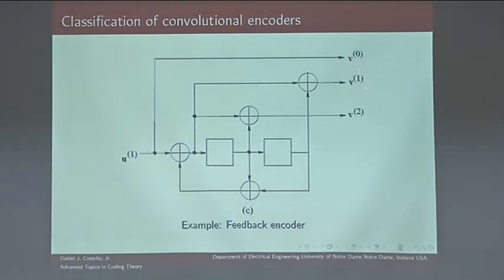And then this output sequence is obtained by taking the output of the second delay stage and adding the input to the shift register. So the numerator polynomial for this would be 1 plus d squared. There's no connection from the 1 time unit delay, no connection from here up to here, so we miss the d term.